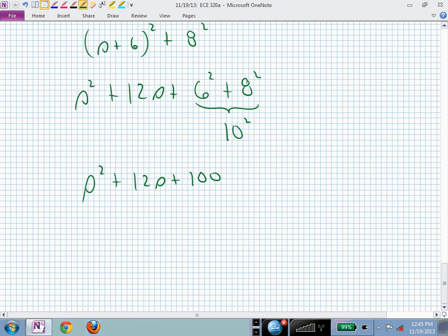If we know we have complex roots, then we like to parameterize that as a quadratic that is s squared plus 2 zeta omega sub n s plus omega sub n squared. That's the factorization that we're going to use. So we need it to be monic. We need the leading coefficient of s squared to be 1. And then we write it as s squared plus 2 zeta omega sub n s plus omega sub n squared. This omega sub n is our natural frequency, which is different than the damped frequency.